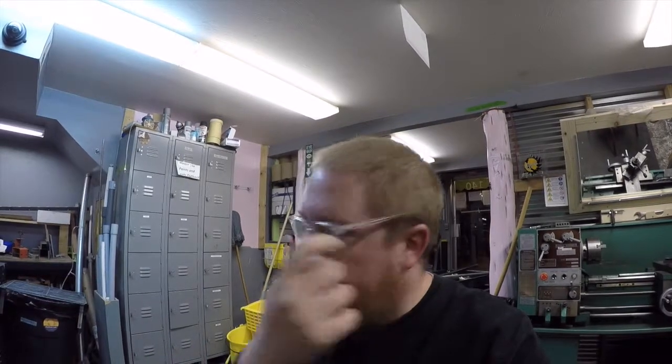Here's something really important to the operation of this machine. Now I said that you can just give it coordinates, X, 5, Y, 0.2, stuff like that, and the machine will go there. But in order for that to be useful, the machine has to have a reference for where 0 is. So it can't go plus 1 inch if it doesn't know where to go plus 1 inch from. That's where this comes into play.